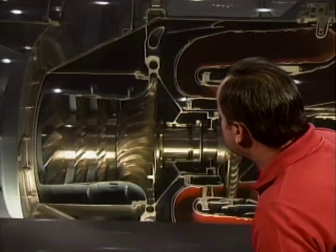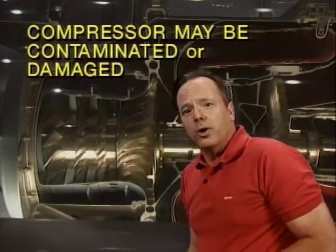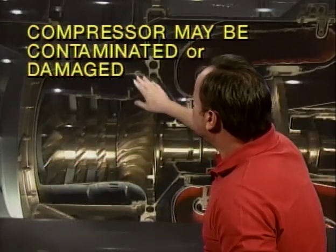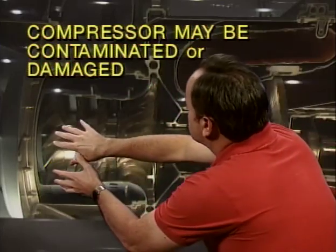Now, let's assume that you have a turbine engine and you're at takeoff EPR, but what you find is you reach the EGT limits. The engine gets too hot before you get the proper thrust. You can't reach takeoff EPR. What would this tell you? Well, it could be an indication that the compressor blades themselves are either contaminated or damaged, because these compressor blades are airfoils and they're dependent on the smooth flow of air over these airfoils. And if the blades are contaminated or damaged, instead of compressing the air, they'll tend to heat the air, and they also might have compressor stall, and that'd be a very bad thing. And therefore, the compressor is less efficient.